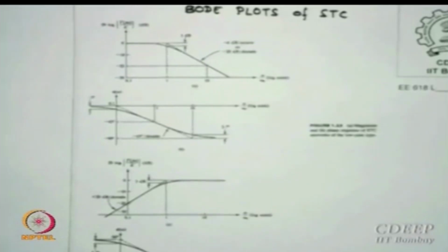All that Bode did, of course there is a lot of theory which you read in a control system course, and there all the worries are only for stability. This was only shown for a 100% stable system. We like to see in real life, when we look at op-amp design, if there is an instability, how do you get rid of it and when the instability occurs. We will see in the case of a small feedback system that instability starts when something happens in the feedback, and in an op-amp we want to avoid it because we want to make the amplifier stable.